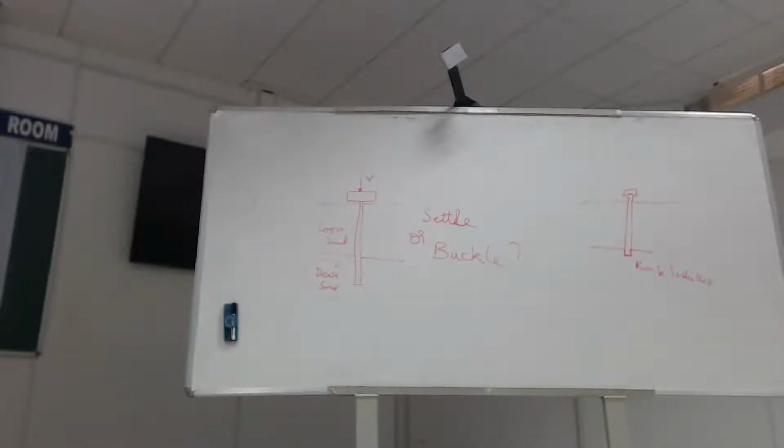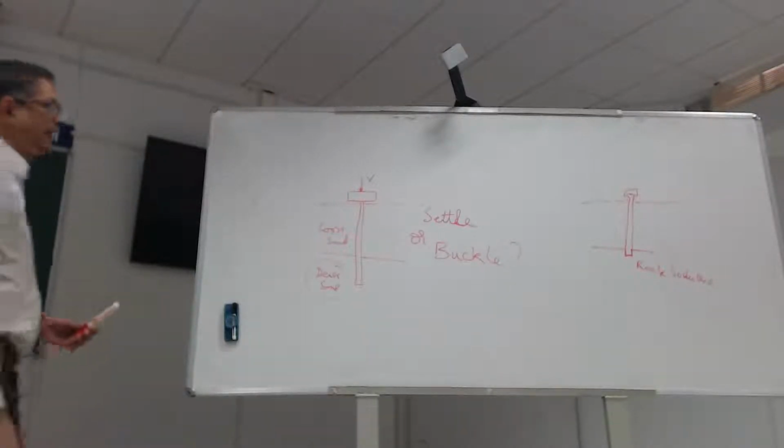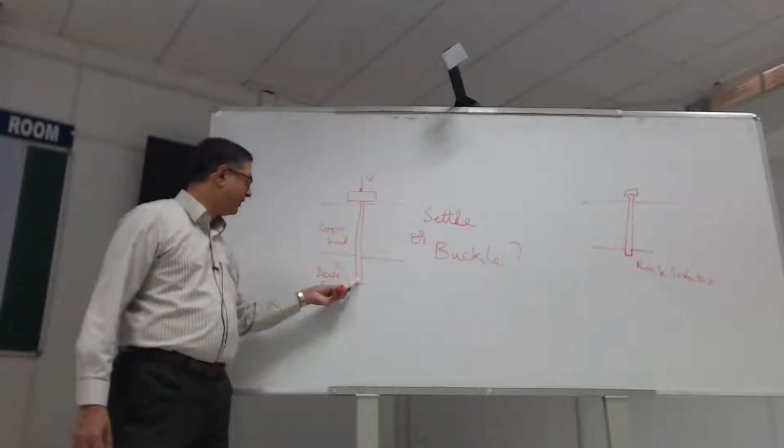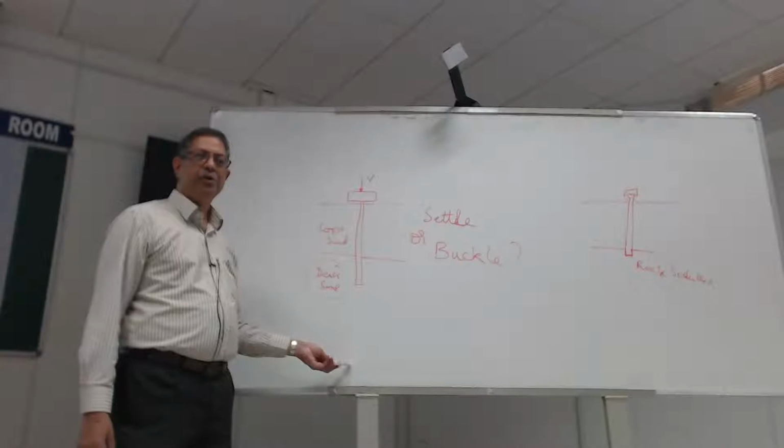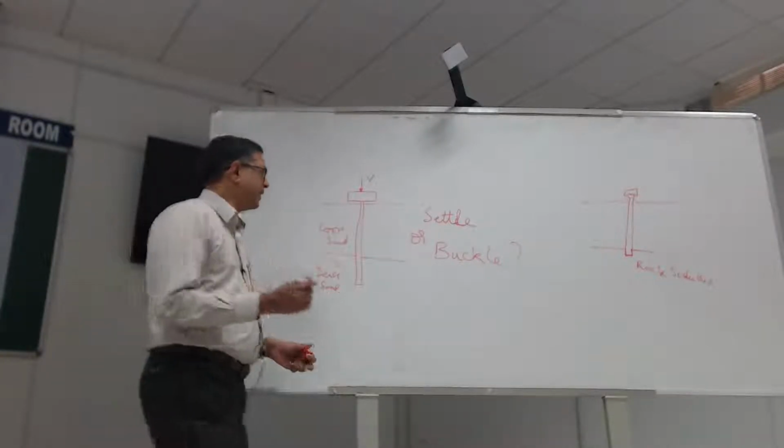But if you ask your practicing colleagues, how many piles in the world, or at least in India, are rock socketed? Get a percentage. It's about 5%, maybe 10% if you push it, because often the pile lengths you need don't reach the bedrock. So, although we made a lot of noise about buckling and looked at all the complications, in practice, either I need quite a long length into dense sand to make this happen. So, what we're saying is to get buckling,